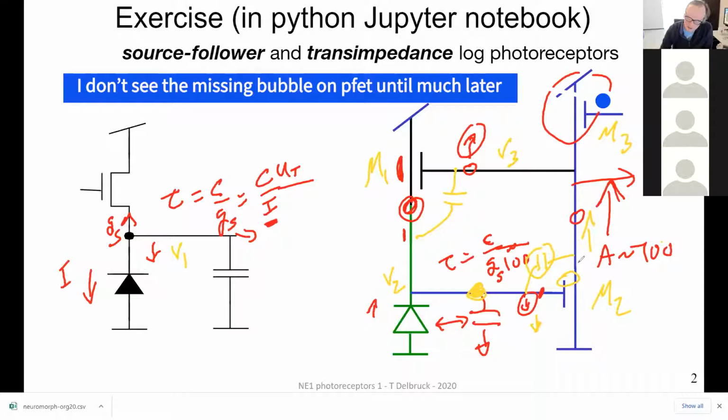But in your simulation, you're going to introduce an early voltage into this transistor here, GD, which is equal to the saturation current divided by the early voltage. Otherwise, it mathematically doesn't work. You can't have 2 perfect current sources with different currents fighting it out. You can't find a solution for that because they're not compatible.